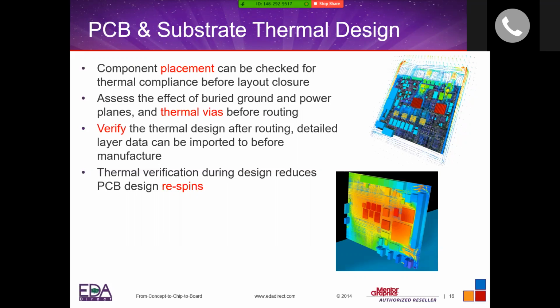So what is the final solution? That's where you run the thermal simulation and see where the best location would be. And you would also run a signal integrity simulation to see how far apart you can be, okay, to maximize your signal quality as well as minimizing your thermal issues, okay.